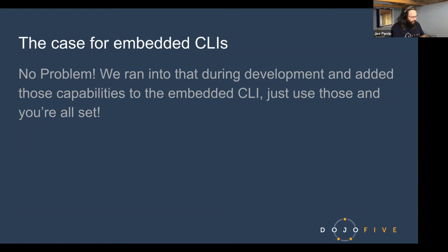That could be all of those things we just talked about, like programming serial numbers or MAC addresses. If you instrument your code to give hooks and expose that functionality through a command line interface, then anybody can use it. A software team who's familiar with how to plug in a UART cable, a hardware team, QA, it goes all the way down the list to somebody doing a customer demo, who you have to tell exactly what to do, right? Make it very easy if they can just plug in one cable.